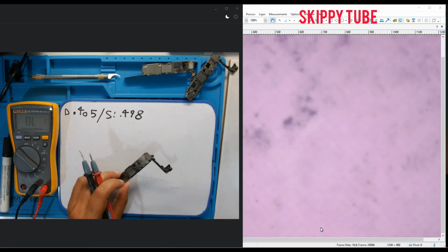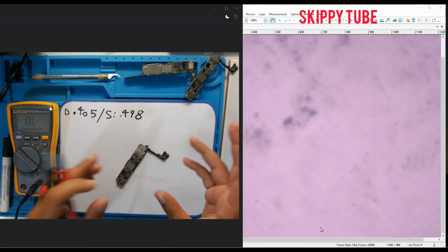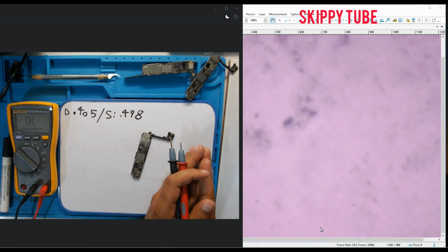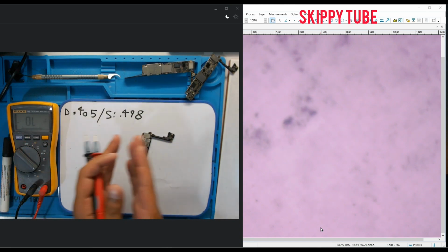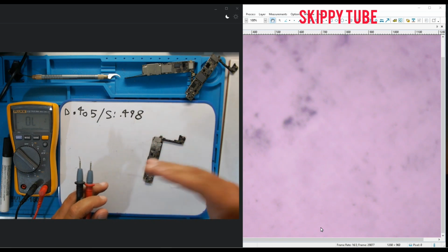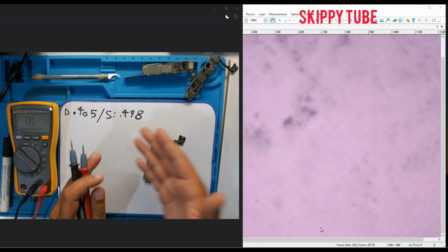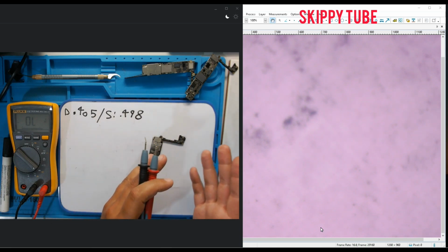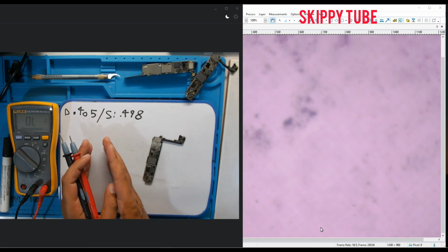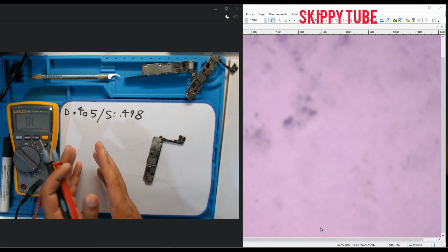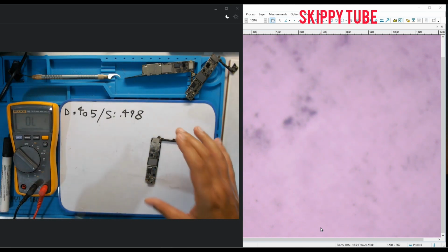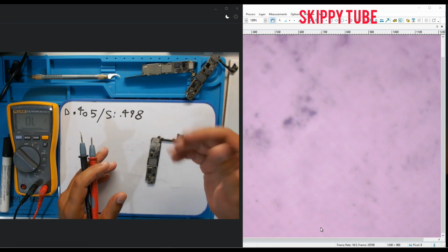Now going to check, because I told you when you check the iPhone you need to check voltage 1 and voltage 2. That means V battery and VCC or VDD main on the iPhone. It doesn't matter if it's Android; you can use this formula on an Android phone like Samsung. You need to find the V bat, and voltage 2 is the V bat or VPH. If you have experience, you can easily find it.